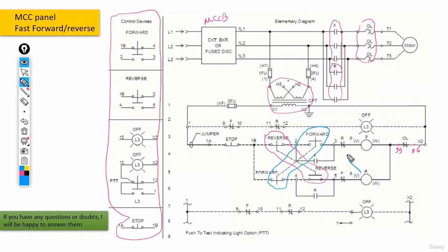And again, we have the closed contacts of each contactor set in the path of the opposite contactor. You can see the signal lamps that function based on how the forward and reverse contactors work. And as I said, the lamps are set on the front panel. Alright guys, so basically this is an example of a forward-reverse circuit that we might find in a motor control center panel, or, in other words, the MCC panel.